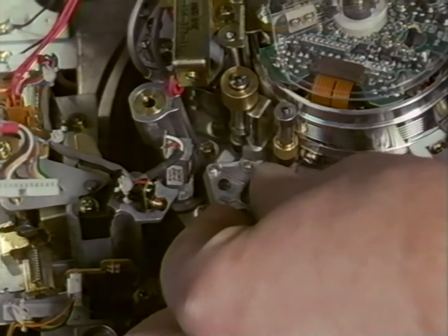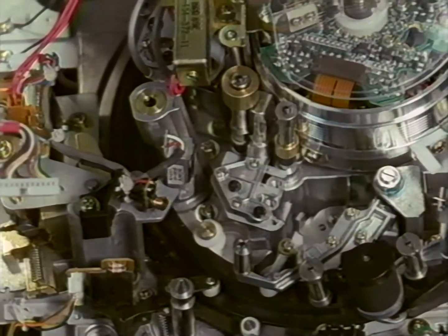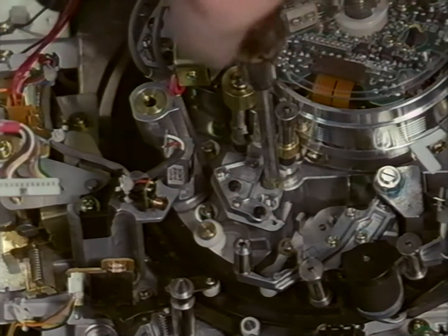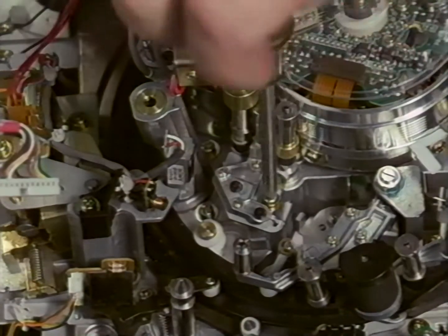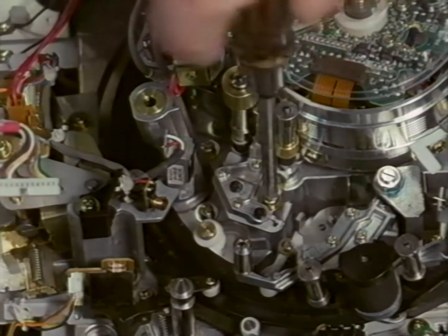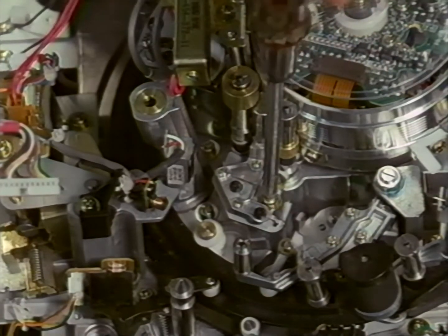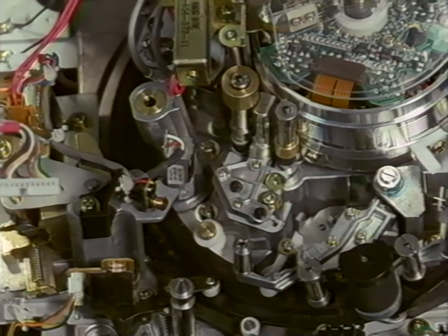The CTL head is moved back into position and the fixing screw and step screw are tightened down. Once the CTL head is completely installed, the adjustments in Section 523 under replacement of the CTL head would need to be accomplished.